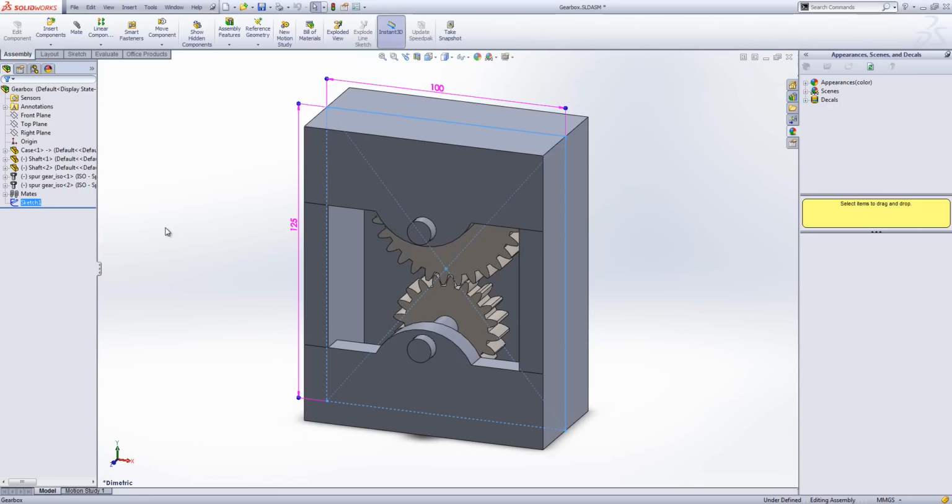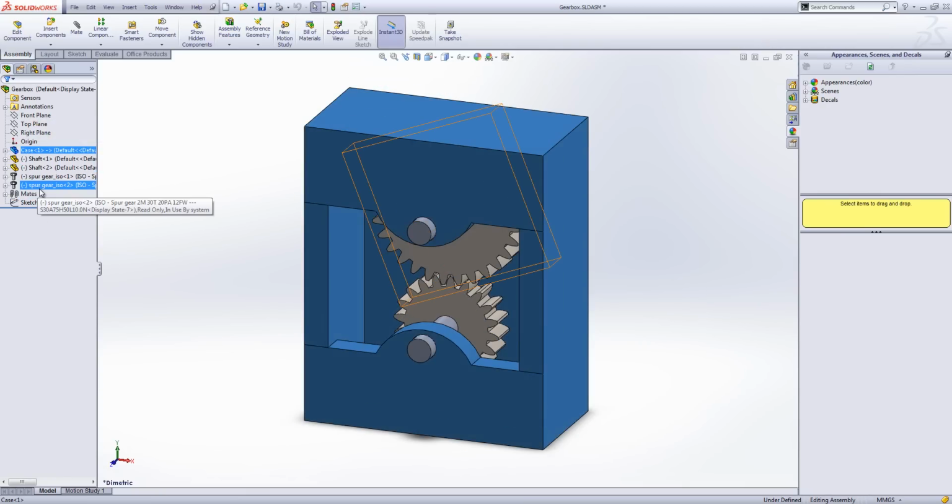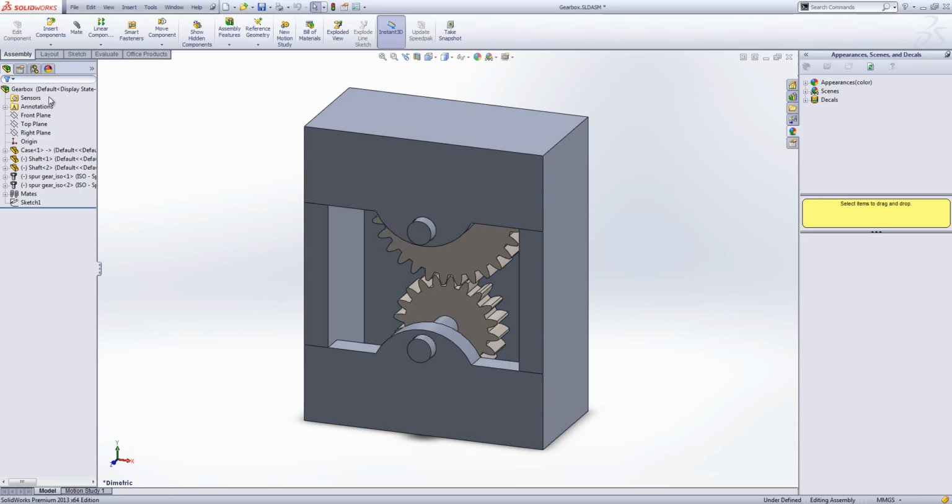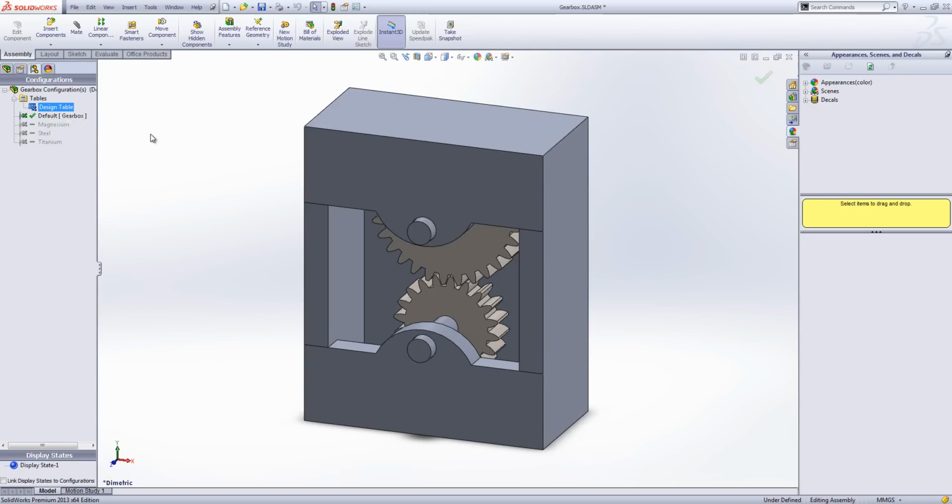Now I can't actually control part parameters directly. So what happens is we have a controlling sketch, and then that controlling sketch controls my case. So my case dimensions equal that controlling sketch dimension. So although I'm not directly driving my component, I can still resize my component based on what is said in the design table. So if I jump into this,